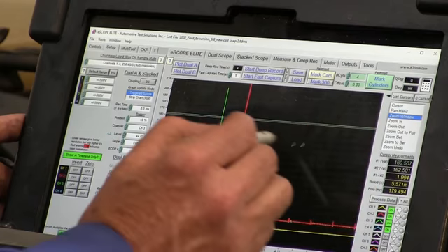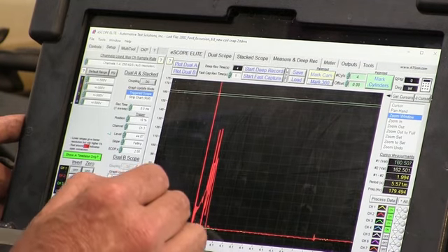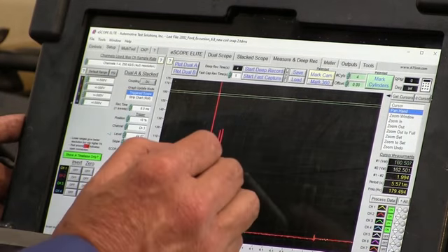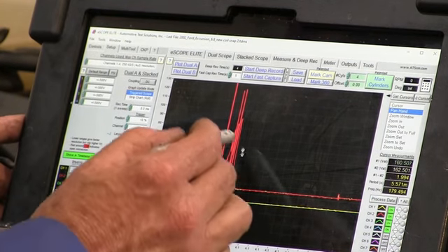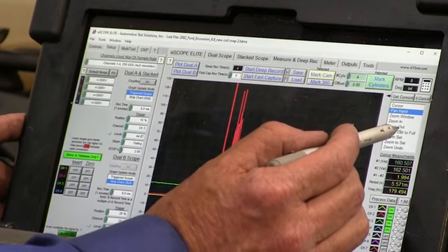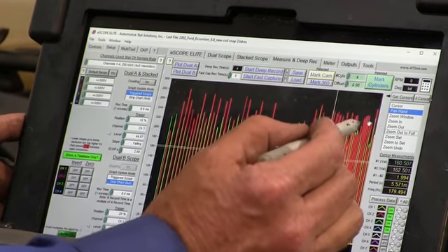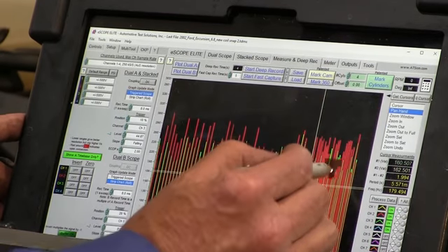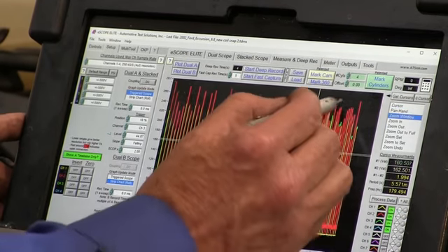And 1's pretty lean right there. So you see how 1 is coming up? It's not nearly as bad as 9 is, but that's lean. So we have a lean cylinder on 2 as well. So we got a couple of cylinders here that look lean, and the car has 200,000 on it, so there's probably lots of lean cylinders would be my guess on this vehicle.